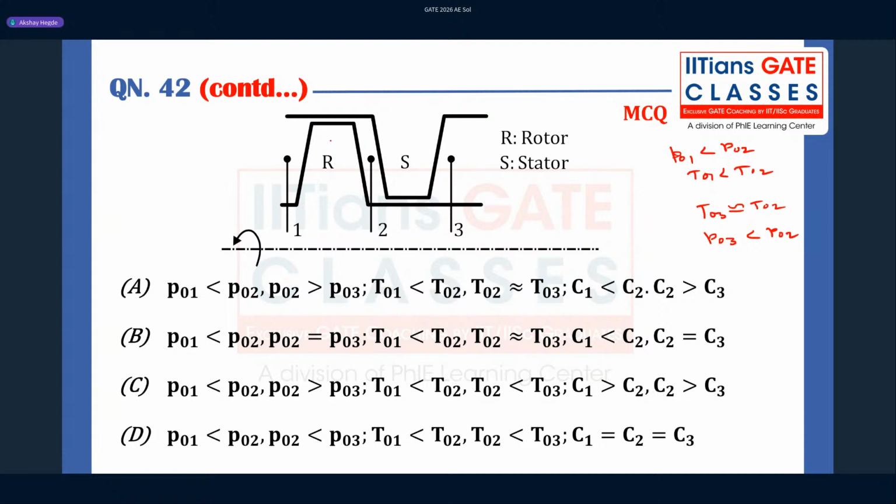Kinetic energy, our absolute kinetic energy. Since it is a rotating machine, I have a flow that is coming in at C1, and as it leaves the rotor, there is C2. Since there is centripetal acceleration as it rotates, C2 is going to be greater than C1. Whereas in the stator, we have energy transformation, because we are allowing the flow to diffuse, go through a diffuser kind of section.